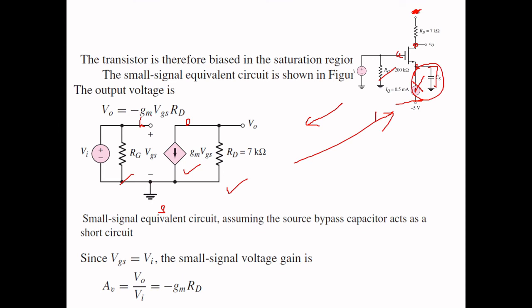So here finally this is a small signal model for this circuit. Here we want to find V0. V0 is nothing but ID into RD. You know the same procedure, you want to short circuit the input loop to find your output resistance. If you short circuit, VGS will become 0 and this also will become 0, so that RD is your output resistance. So your output current is nothing but GM times of VGS into RD. With that, you obtain this output voltage.